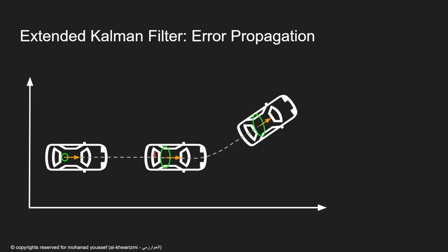This results in that when the vehicle is driving straight forward, we are unsure if it's really straightforward or maybe there is a kind of drift to this position here, or even on the other side. It depends on the sign of the offset of the gyro sensor, for example, or the wheel model that we have. If the vehicle started to take a turn here, then we will have a correlation. So the ellipse will start to have some tilt angle, as you see.